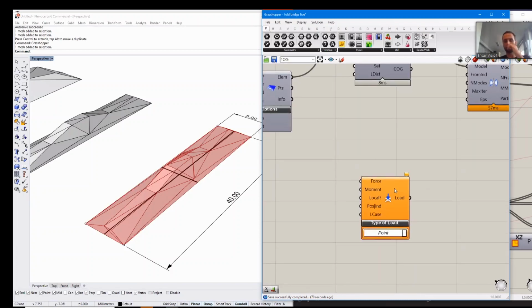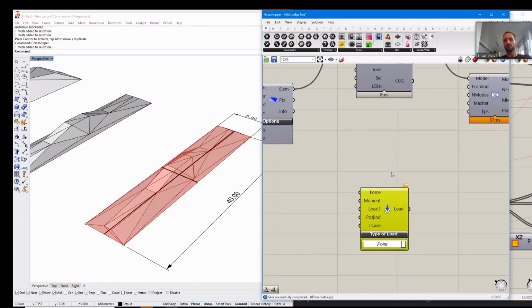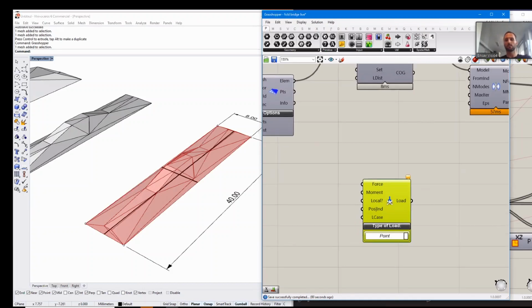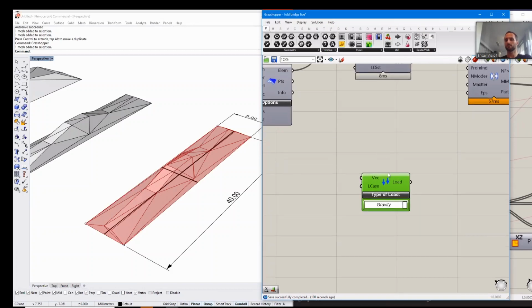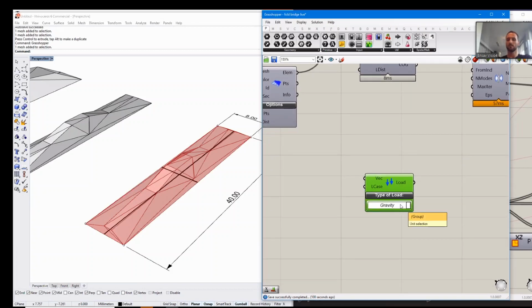This is also, as I mentioned, not unimportant, how you load the structure, because if you just load it by gravity, for instance, if it has lower surface area, the gravity load is also less, which is not really realistic. You have the bridge, usually a pedestrian bridge. If this is a pedestrian bridge, it is governed by the people walking over it and its vibrations, and the people walking over it will always be the same load, right?